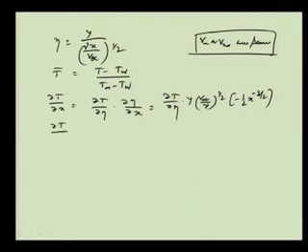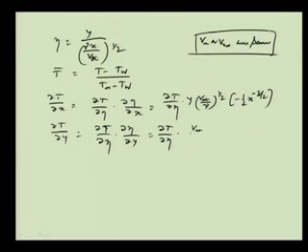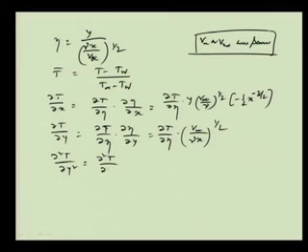These are not simple things, it is only just getting the derivations. It will be ∂T/∂y equal to ∂T/∂eta into ∂eta/∂y, and that is equal to ∂T/∂eta into (V infinity by nu x) whole to the power half, and then we can get ∂²T/∂y² is equal to ∂²T/∂eta² into V infinity by nu x. That is what it is.